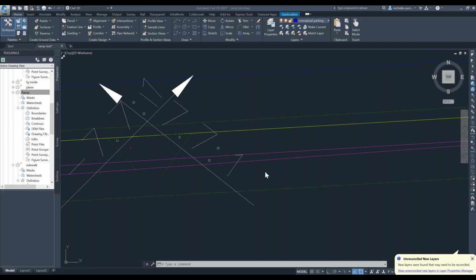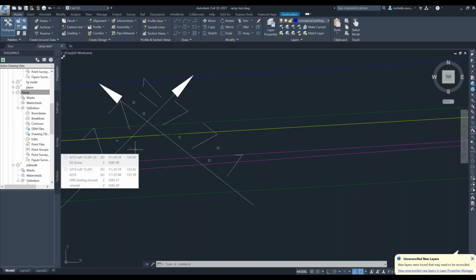It's a good question. We built all of our ramps pretty much the same, and we haven't really had many people comment on them. We do a standard 5-foot width for the flare, which gives us a nice 12-to-1 slope. The only thing we ever really have to worry about is making sure the cross slope from one end of the flare to the other doesn't throw them out of compliance. We spend a little bit more time in grading for ADA than the rest of it, which helps keep down comments and issues in construction.